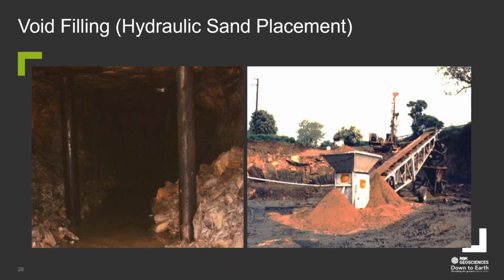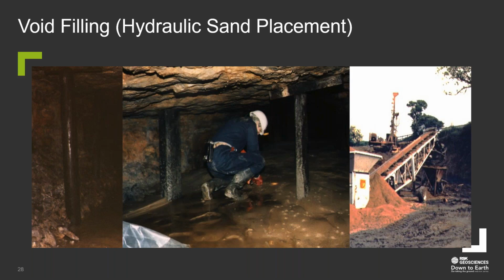Moving on, here's a hydraulic sand placement underground in the northeast of England in a fire clay mine. Huge void space, very expensive, would not be able to make that a viable site by just filling it with PFA cement grout. So instead of that, put boreholes in. You can see the sand hopper, a sand conveyor, a water jet hopper, and the borehole, an 8-inch, 200mm diameter hole down, intersecting the void spaces.